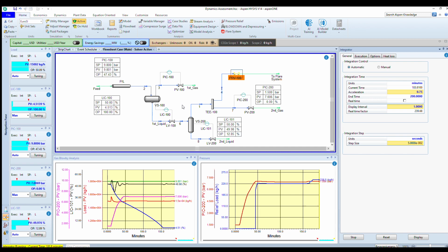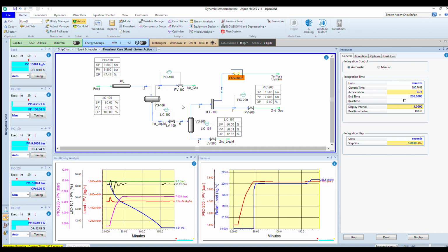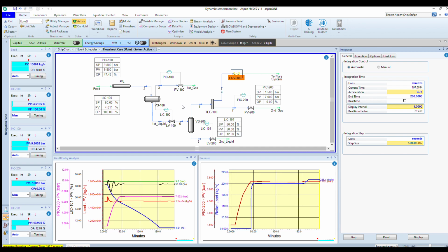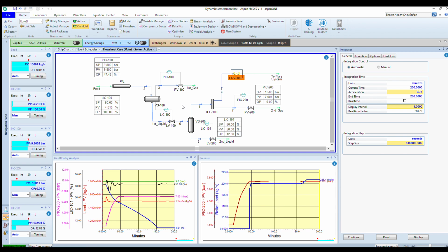Though I have added unjustified chronology and setup to this scenario, I have assumed double jeopardy. This valve will fail and at the same time this valve will fail. The resultant relief load is so much less compared to the steady state assessment.